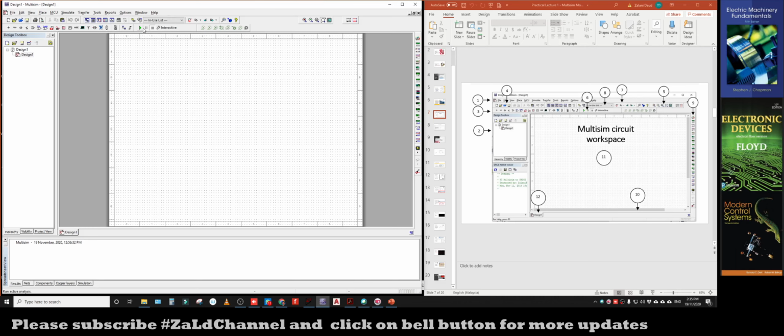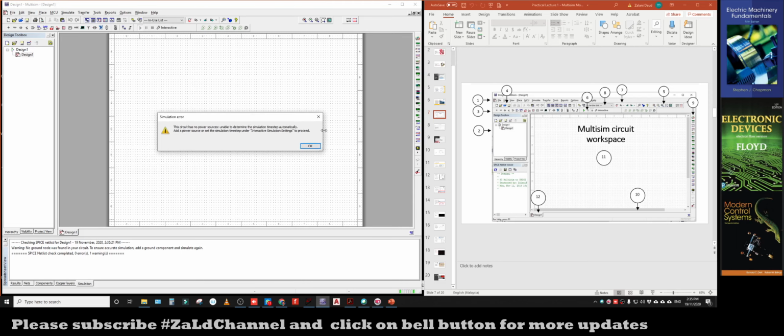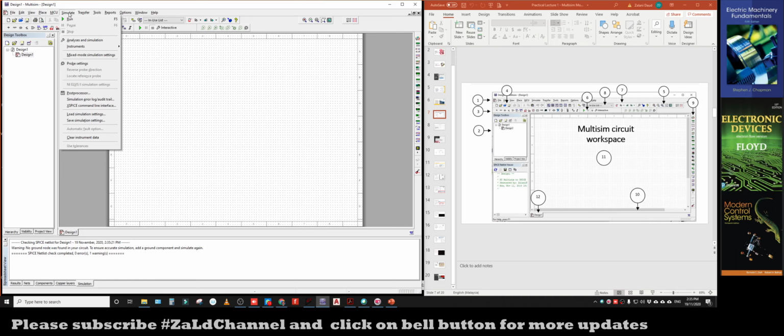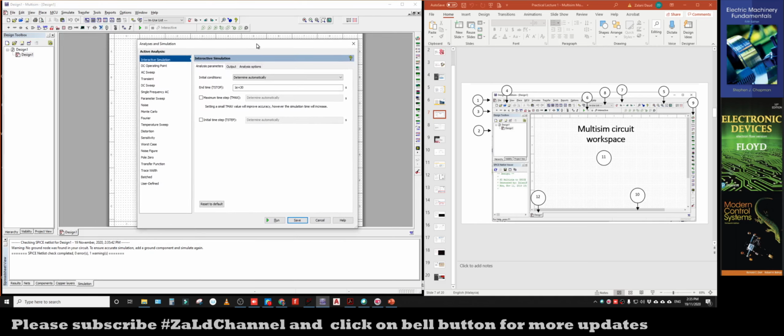The green one is the simulation button. Once you complete drawing your circuit here, you can just click on this simulation button, which is to run the simulation. So at the moment, I don't have any circuit, so a simulation error will appear like this. You can also access this simulation button from simulate. Then from simulate, you can go to analyze and simulation. So go to the analyze and simulation.